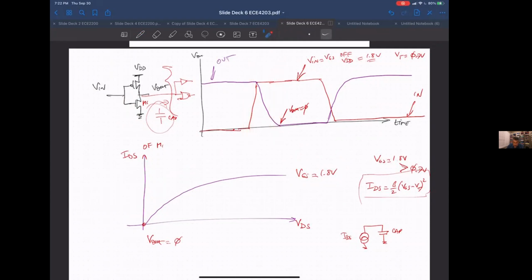Typically your rise and fall times are only a small portion of your total waveform. So this will matter. And then the PMOS current matters in this region, the on currents. So basically the on currents will decide how fast you transition from low to high and high to low, okay? After that, your on current doesn't matter, just in these transitions.